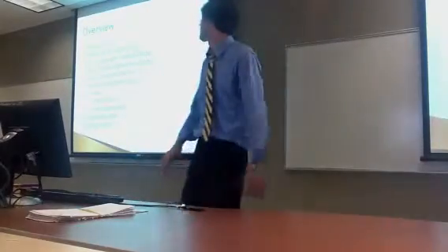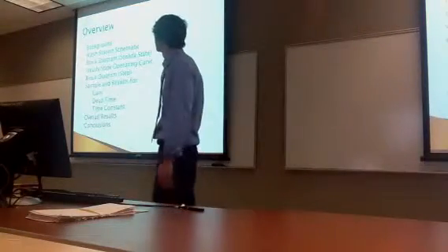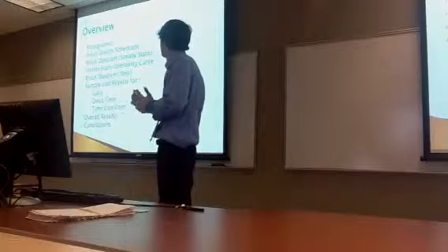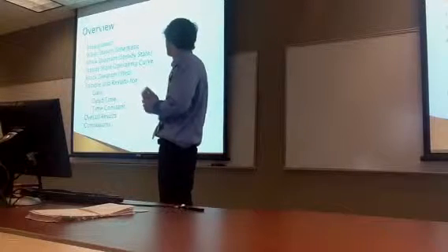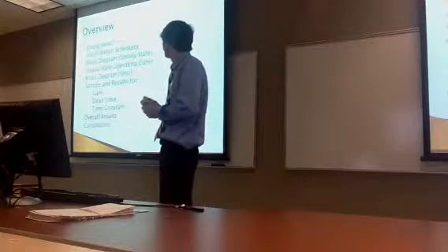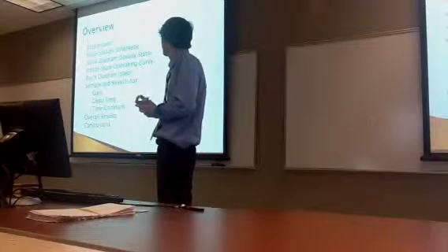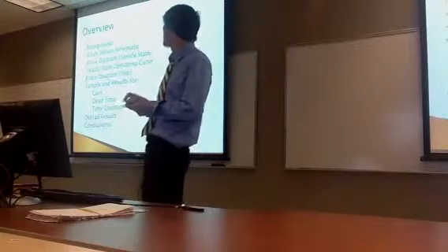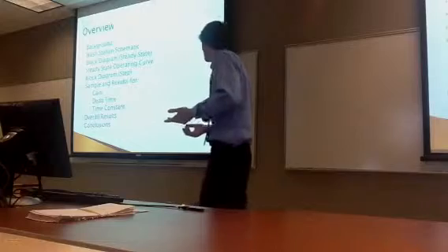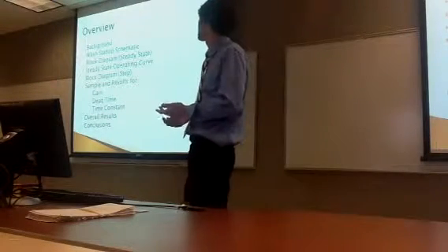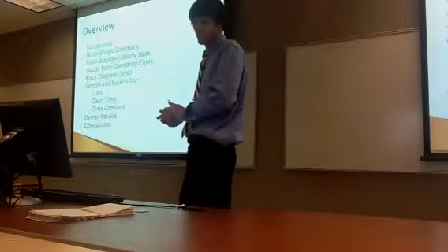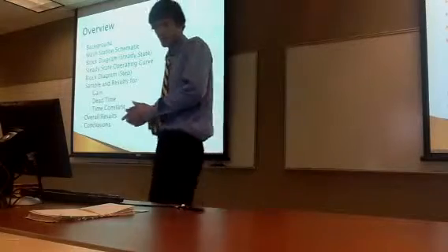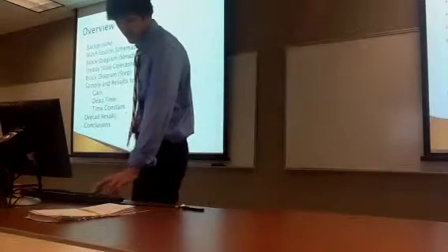A little bit of an overview. We'll go over the background, look over the schematic, and look at both block diagrams for the steady state and step diagram. We'll give you the operating curve, and I'm going to go over how you find the gain, dead time, and time constants, give you the results of each one of our tests, and then wrap it up with conclusions.